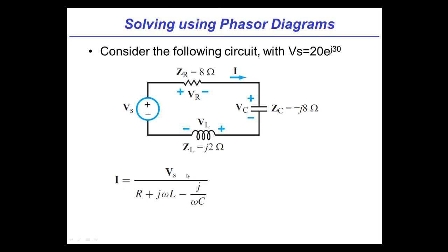Now, because we know that inductors, resistors, and capacitors have different relationships between voltage and current, for that same current, each of these will have a different phase offset for their own voltage. Right. So let's go ahead and set that up, okay? So what we can do is the first step, which you talked about, which is we can calculate what the current is, okay?